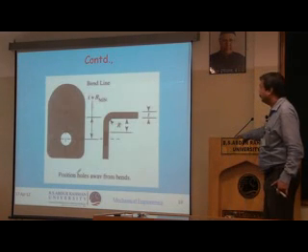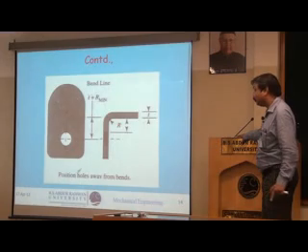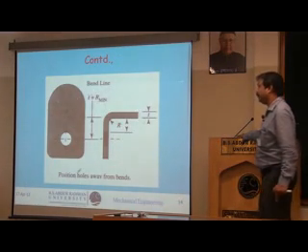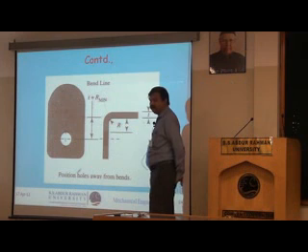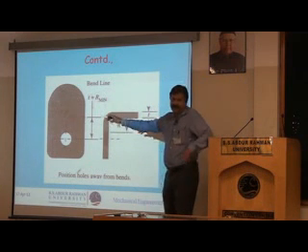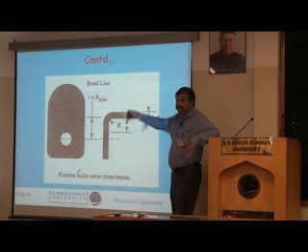Next slide please. When you are punching holes and bending, the bending radius must have a minimum value, and you should position the holes away from the bends. The hole must be as far from the bend as possible, because the hole is a section of weakness, and when bending takes place, it may not bend at the intended section. It may prefer to bend at a weaker section.